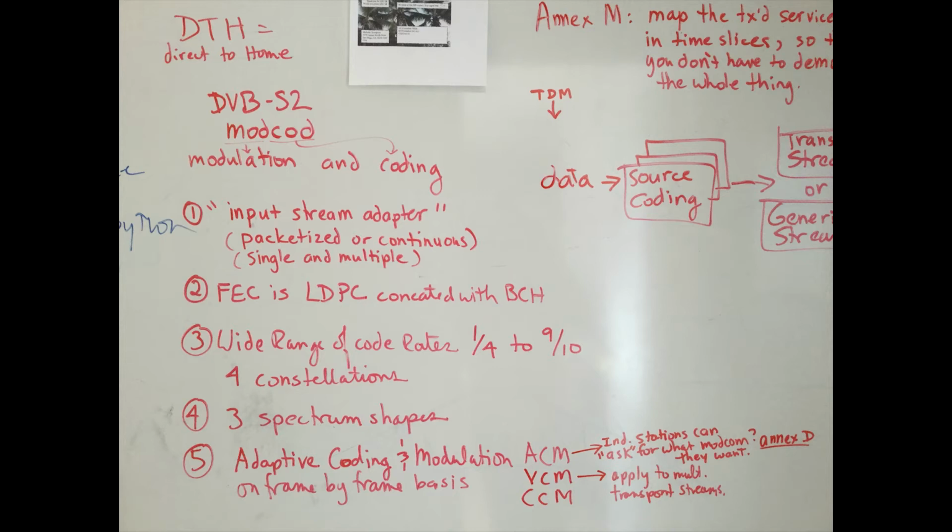4, there is a variety of spectral shaping available to us in DVB-S2. This is a really neat thing. You can change the pulse shape of a transmitted waveform in order to make it better suited for the radio environment it's expecting to be traveling through. Usually this means making it fit into a bandwidth better. You don't get something for nothing though, so being too aggressive with the pulse shaping shows up in other aspects. Our particular shaping offers different levels of raised cosine filtering. DVB-S2X provides additional levels of this type of shaping.